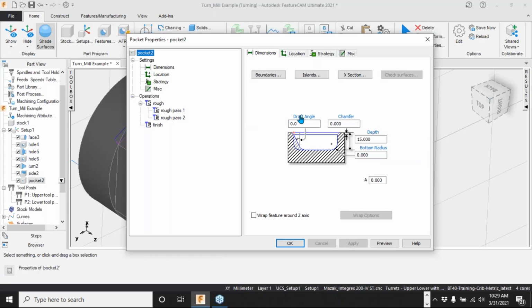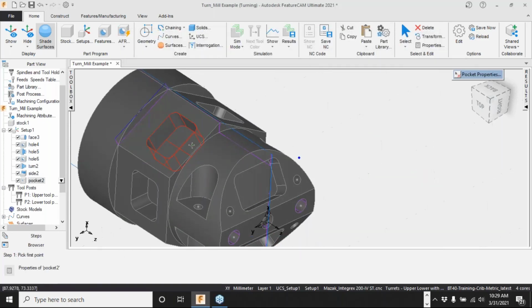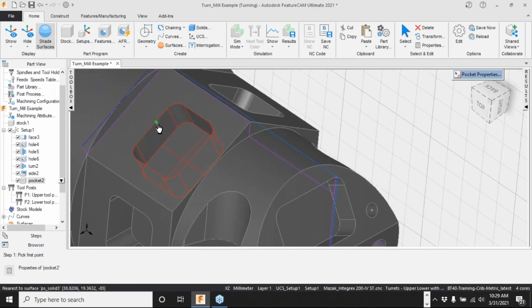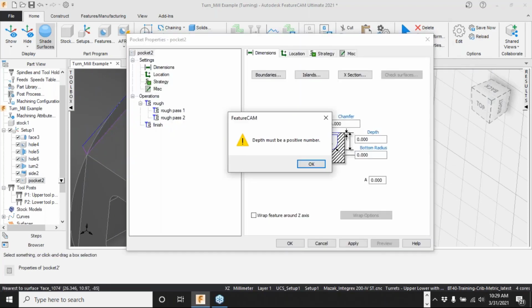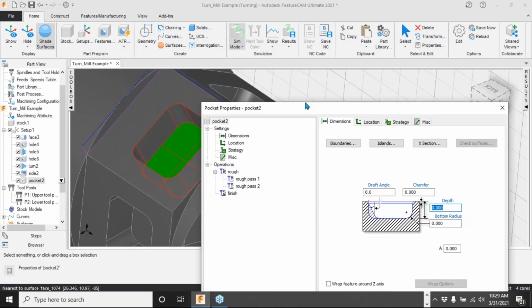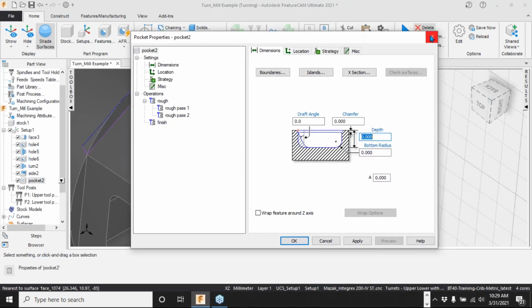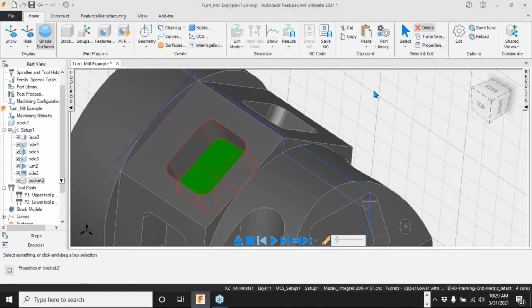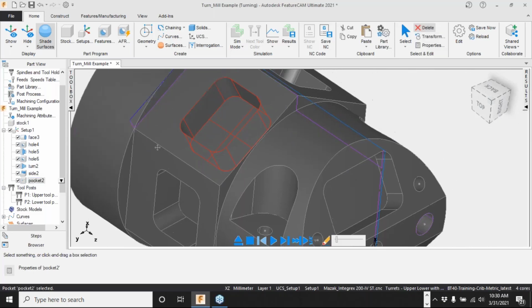Or another handy trick is, do you see how these are highlighted in blue? You're able to pick those names, those titles, and come down here and actually pick a depth. So I can click on that surface, that top surface, and that top surface, and I have a depth. Looks like I picked some of the wrong geometry there. But it automatically knows you're able to pick a lot of that geometry manually.